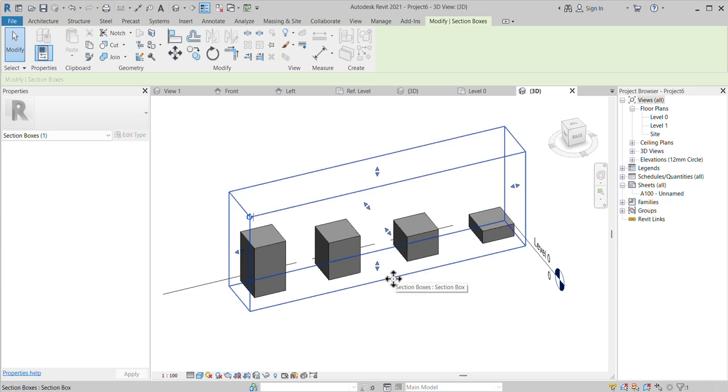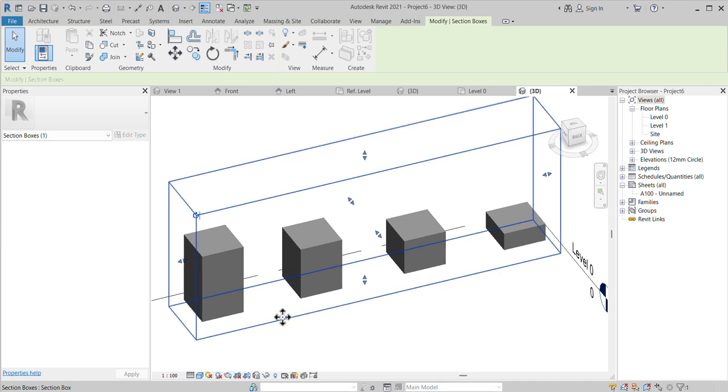Okay. So we can adjust our height or width or anything as per our drawing conditions. Okay. See, for example, when you work on manholes, mostly you have to use this instance parameter because the cover level and invert level are always changing. So you should take care about this. Instance parameter is better. Okay. So this is one example for instance parameter. You can easily understand how the instance parameter is working.